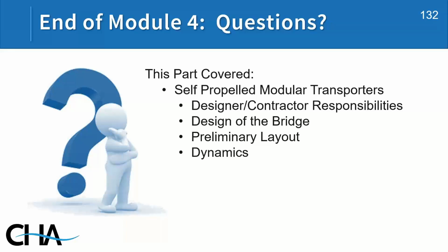Did you study any about the bridge SPMT interaction? That question has been asked before, and really what it comes down to is, again, the hypothesis of the research was that the SPMT driving down the road, starting and stopping, is similar to an earthquake. In an earthquake, the ground motion is at the ground level. So we say, well, as acceleration is at the ground level, let's take those accelerations and apply them to the false work in the bridge.